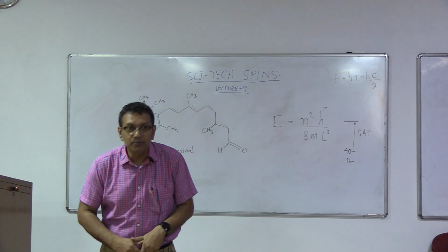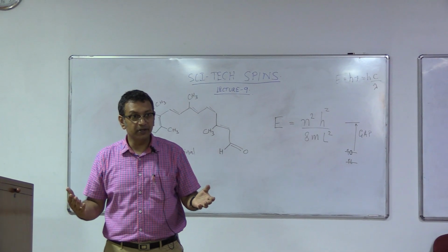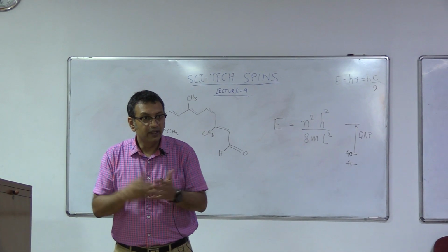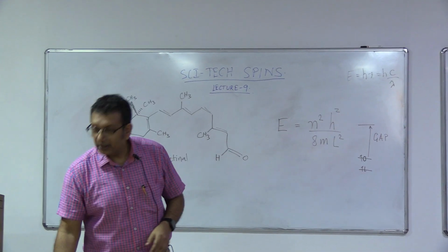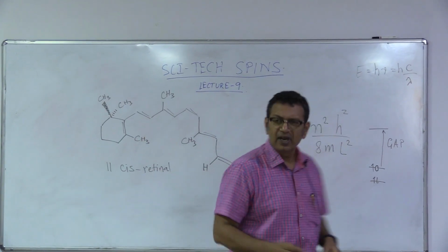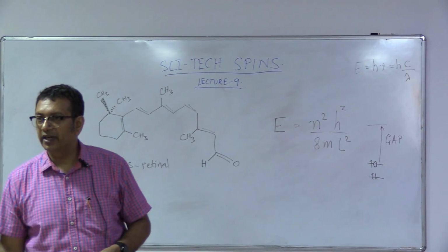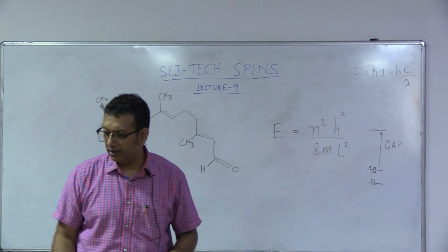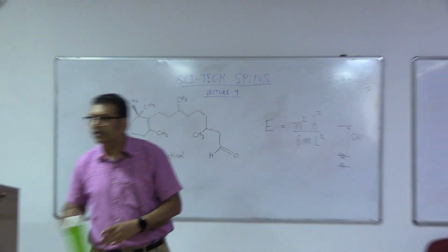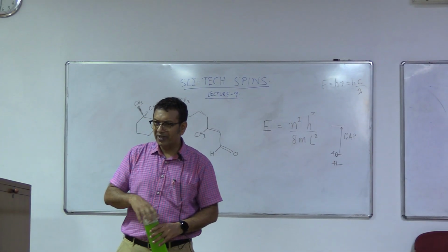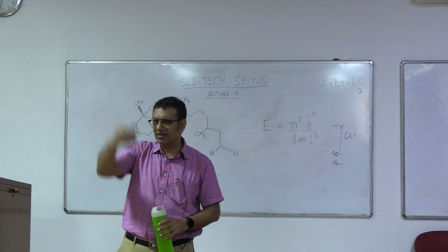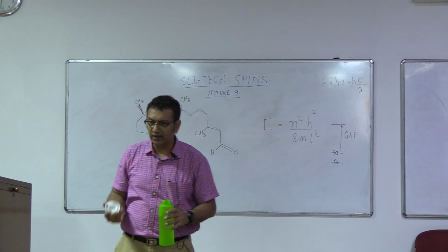Anything which has energy more than that, wavelength up to 1100 nanometers, would be detected by silicon. Well, practically it's not 1100, it comes to about 900, 950 nanometers. And these are typically, I think, 850 nanometers, the commercially available ones. These are very cheap infrared things, and the TV has the same sensor, and they are all built on silicon.